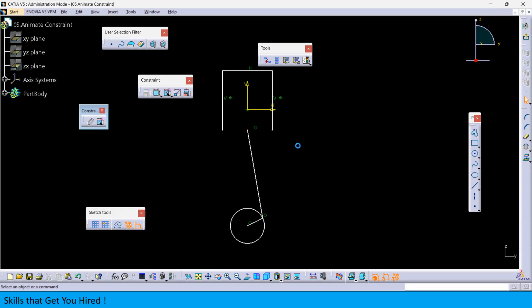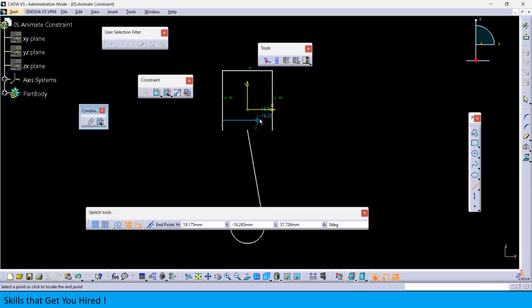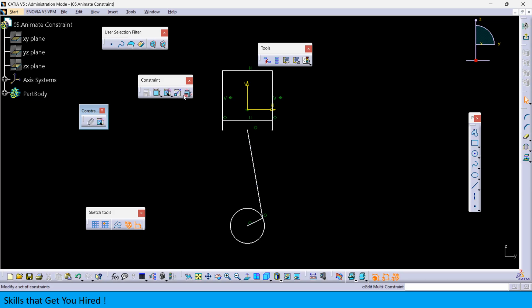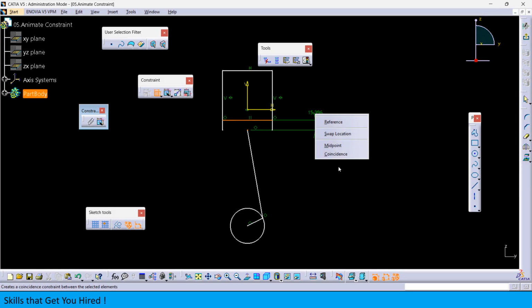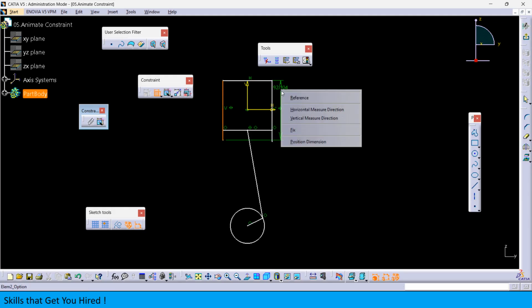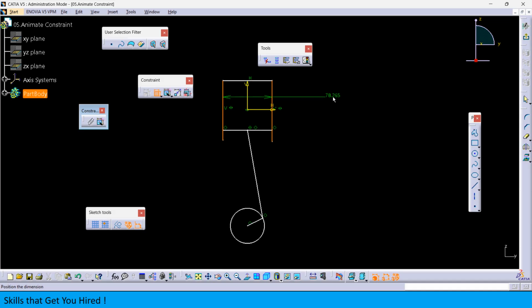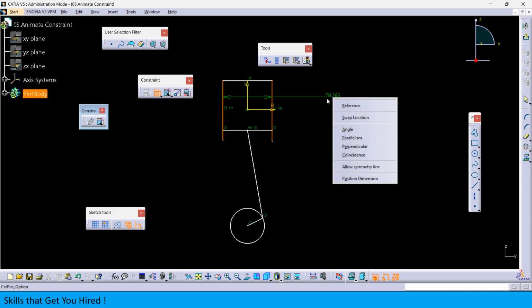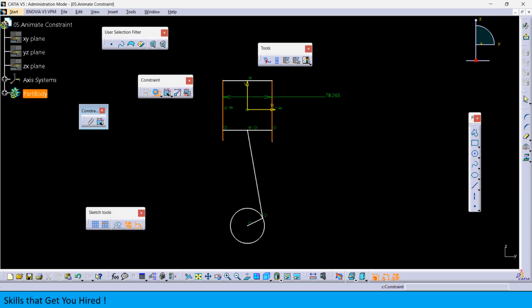After that what I will do, I'll just delete this line entity, and here I'm creating a line like this. Now I'm trying to connect this line over this point. Now you see here, so these two lines become equal that are required. So I just click both the lines, sorry, right click here and give the relation to equal entity. So it's not there. Okay, fine.